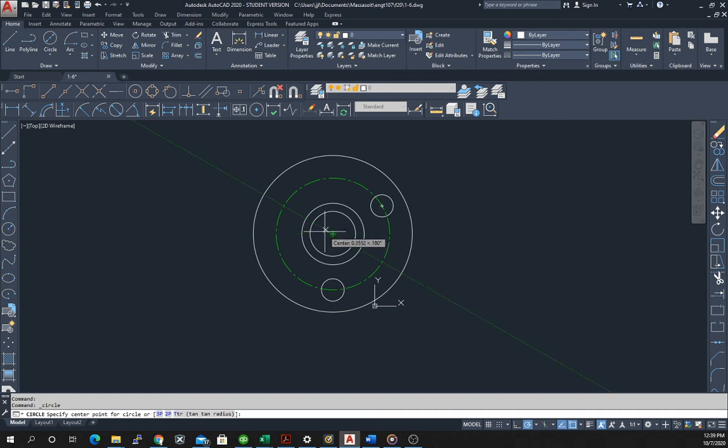So this is our 180, so this would be our 150. So all I do is move up to the point where I'm at this intersection. I hit my mouse button. Now I place the circle. That does place the center of the circle, and I type 1 to enter the diameter. So now I place the 3 circles.